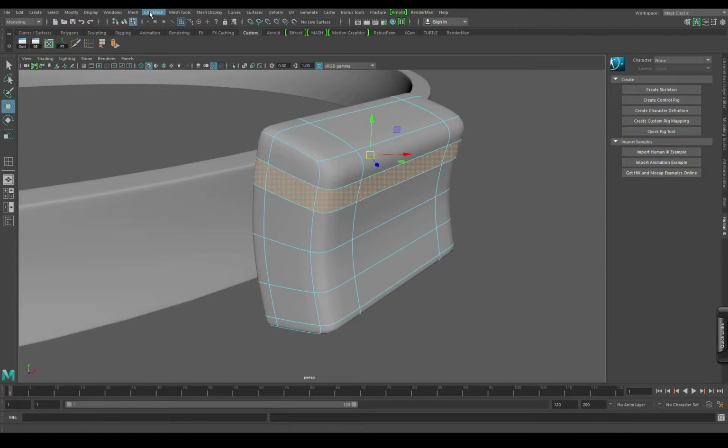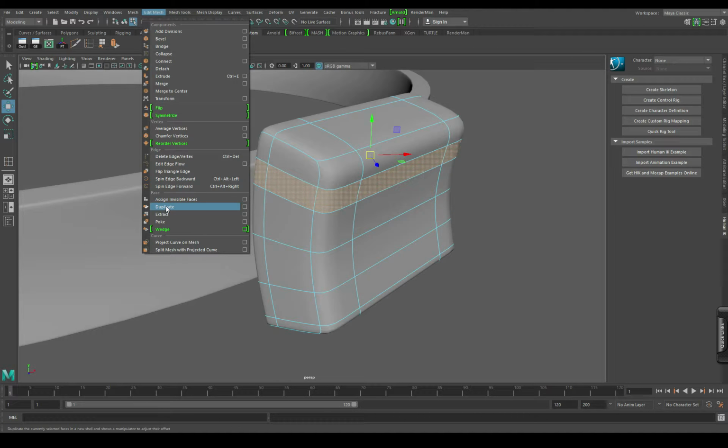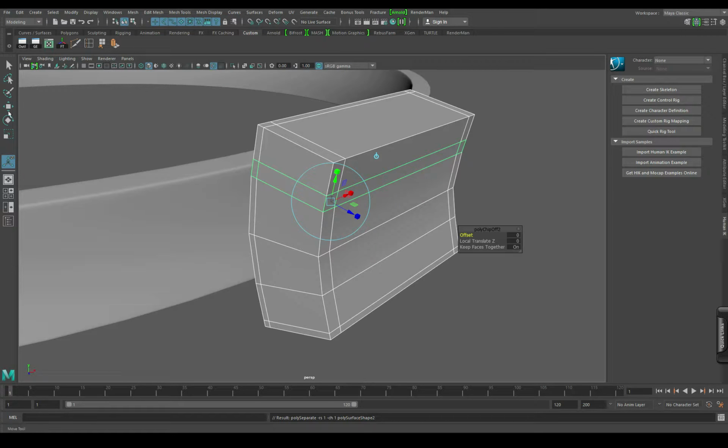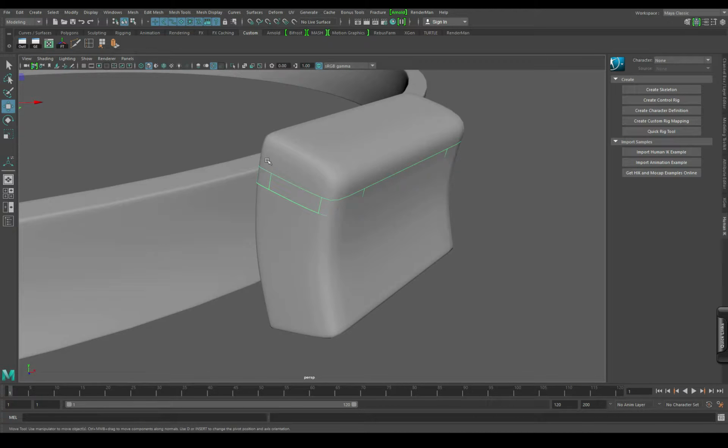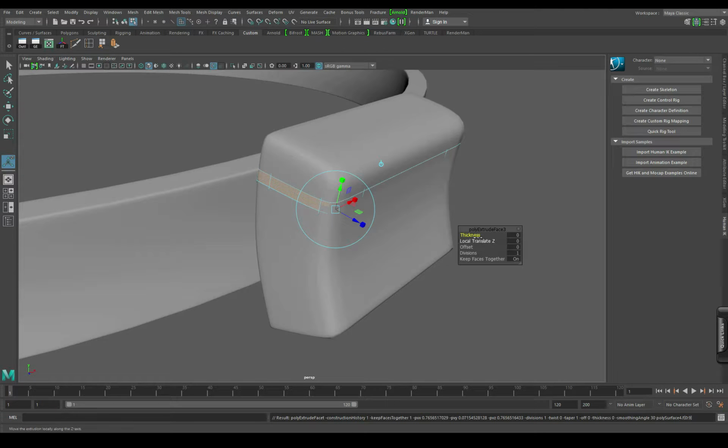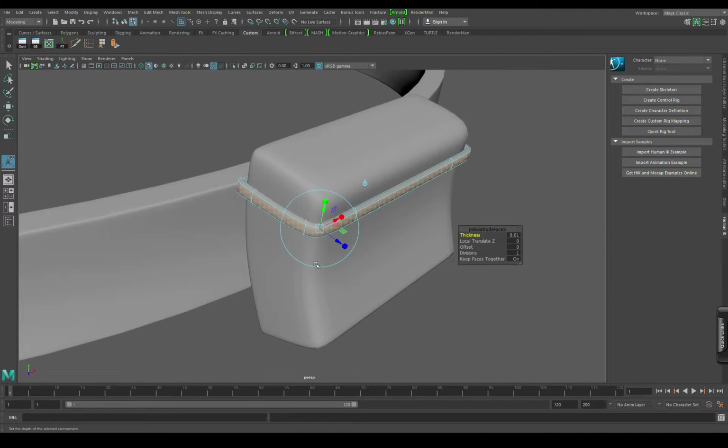Okay, so now I'm going to edit mesh that. I'm going to duplicate that too. Boom, go back to object mode, move. I'm going to hit 3 on the keyboard. I'm going to hold, so it smooths everything, and I'm going to hold down control and just deselect that part. And then from there, once again, I can extrude. And I'm going to extrude it out thickness, hold down control, and just a little bit, so it gives me a kind of a cool thing. If it's too much, just push it back in with your thickness.